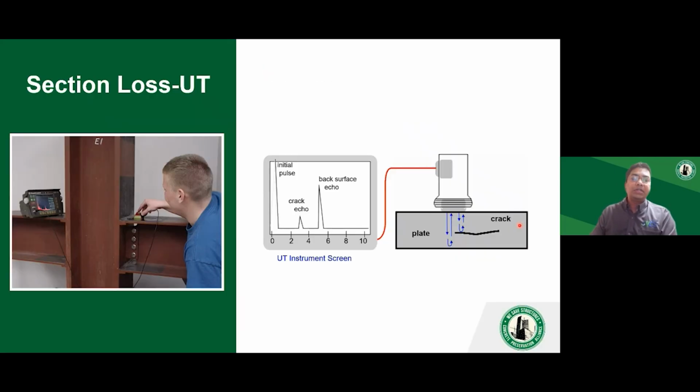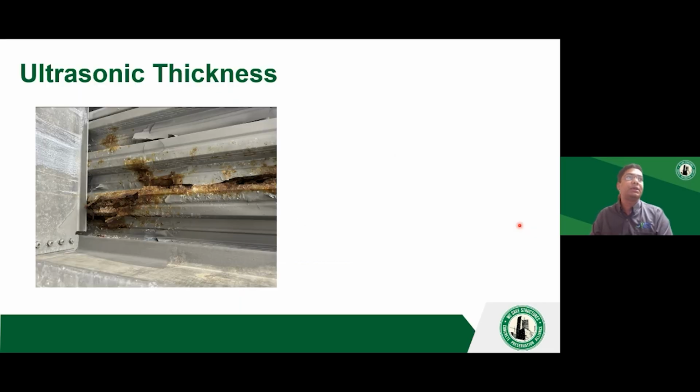Now, we have been talking about steel that was exposed or that is exposed to concrete. In some cases, we are dealing with steel or alloys that are exposed to air. Air is a really bad electrolyte when it comes to testing, and there's only so much we can do about it. One of the few techniques we can use is ultrasonic thickness measurements, where you can just measure what's the remaining section of those air exposed steel or alloys if you have been experiencing any section loss, or if there are any internal defects that are present in your steel members.